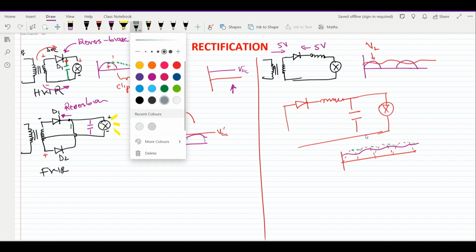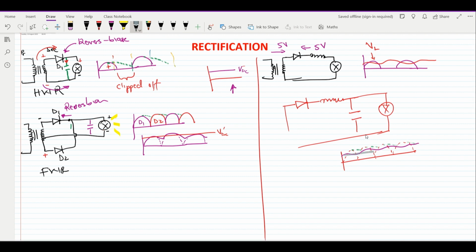We want to achieve DC. This is what we want to achieve. So we are getting closer. Now, what can completely achieve this? Let us see what happens when we put another capacitor before the inductor, changing this to an LC pi filter.